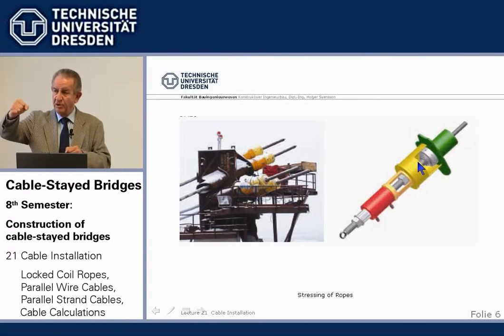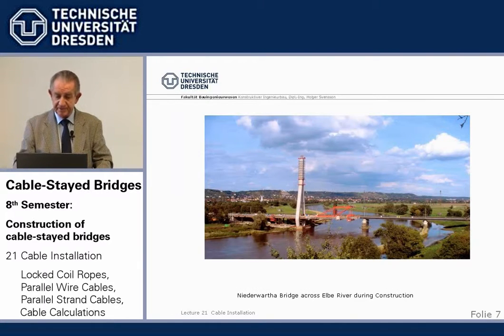So we pull, the support nut is forwarded, then the cable rests on the pull rod and support nut, the jack is retracted, and so on. So it goes in steps of something like 25 centimeters.